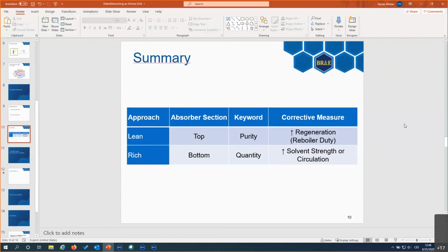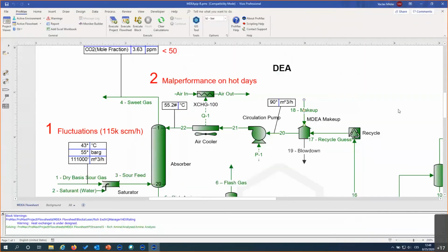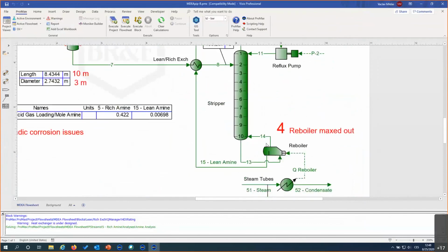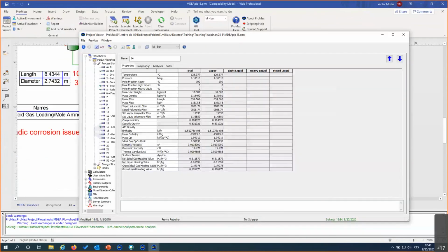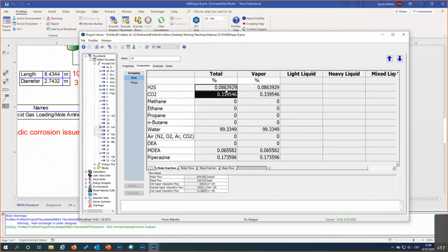One other indication of this is to take a look at the vapor stream coming from the reboiler and see how much H2S and CO2 you have here. Especially CO2, if it's present at high concentrations, can be very corrosive. And so the corrosion can eat your reboiler together with the bottom stages if the stripping is happening too much in the bottom, if you have too high a concentration of H2S and CO2 there.